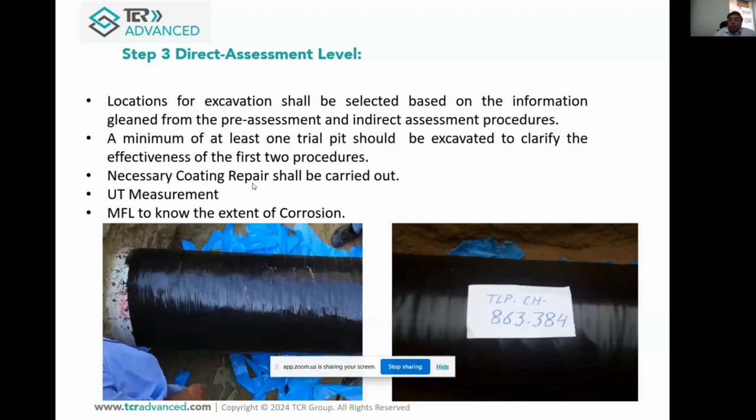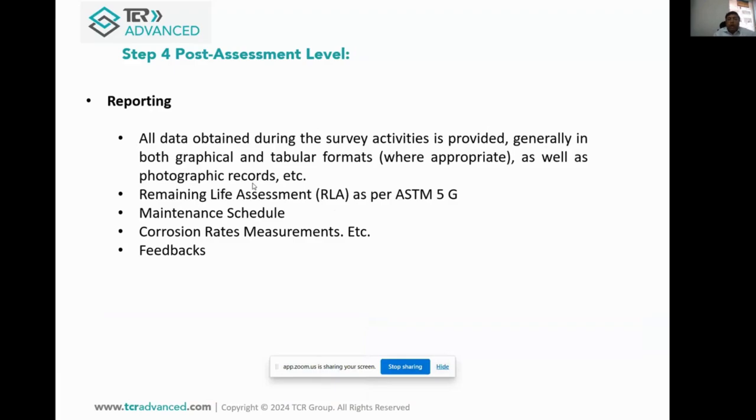So this is typical, how the pipeline is seen after repair, when we found the coating defect and repaired it. So the idea is, in our initial slide, I told you cathodic protection is a secondary corrosion prevention method which works on top of coating. So, cathodic protection systems are designed for a percentage of coating defect or coating factor, right?